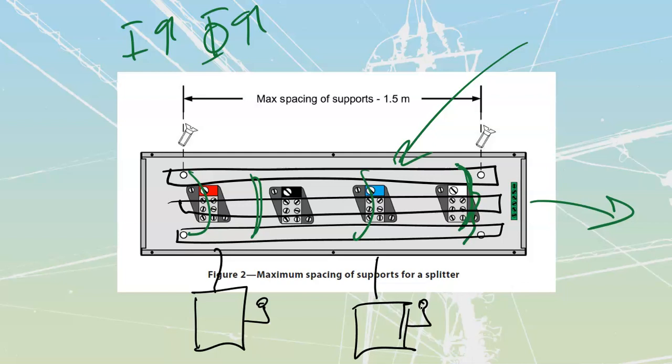If it is an area that is termed as being dead, the majority of BC doesn't actually need to have seismic. But if it is inside of an area like Richmond or Vancouver Island, that's right along the coast and along our subduction zones here, they will require it, and then the engineers are going to inspect that. What it needs to do is just prevent components, by and large, from falling more than a foot. They're allowed to have a little drop. If you get a T-bar ceiling and something drops out, it's allowed to drop up to about a foot or swing down about a foot, but that's going to be about it. These are going to be specified by engineers once again, and it's going to be just external mounting, or external ties that we're going to put to our devices in case there would be failure of the structure.